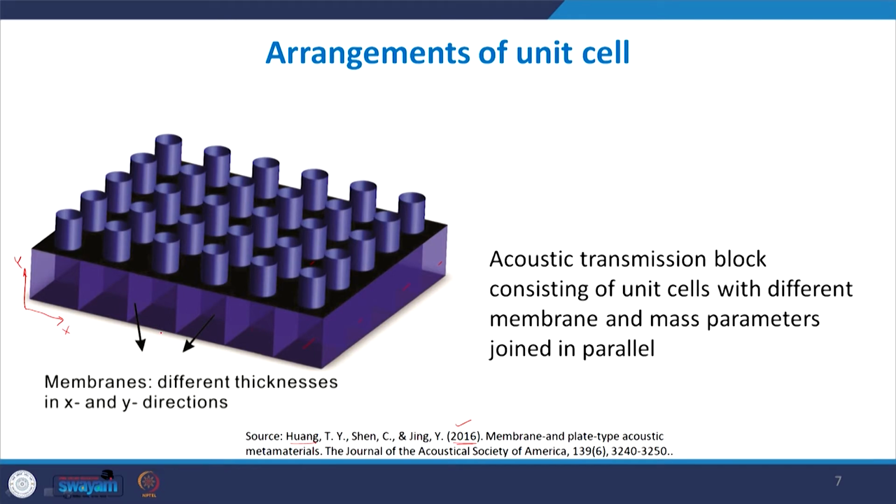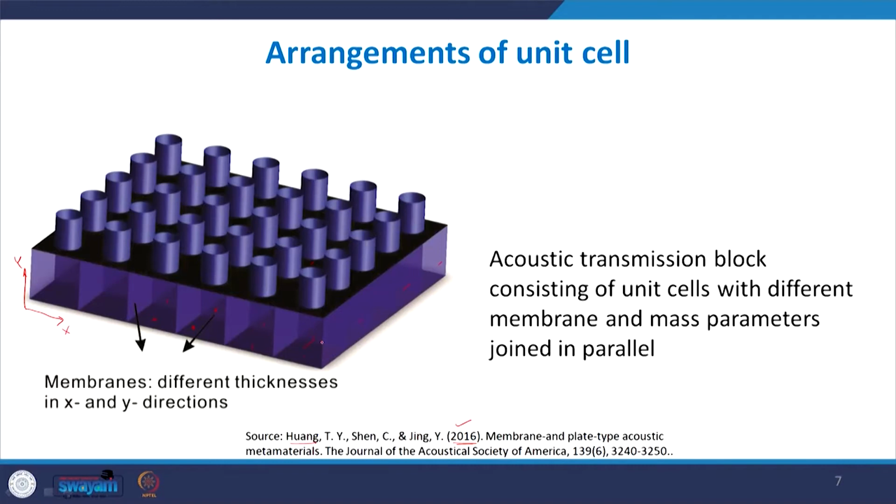So, here the membranes along the y plane. So, this membrane, this membrane, this membrane and so on, the membranes which are in darker colors. Here the thickness is going to be different where they have a higher value, and the membranes that are perpendicular to x plane, they have a lower thickness value. So, the membrane parameters are different for different directions, so that we get different noise control in different directions. So, this is the kind of innovative arrangement that was proposed.